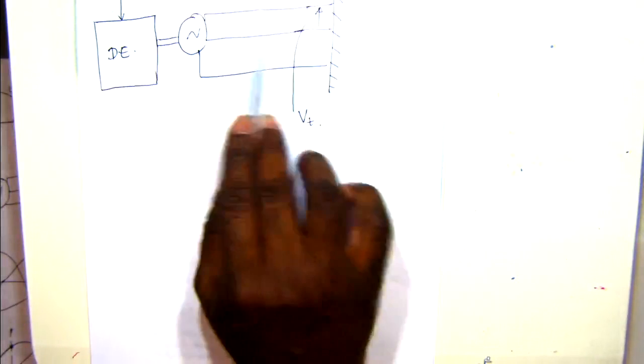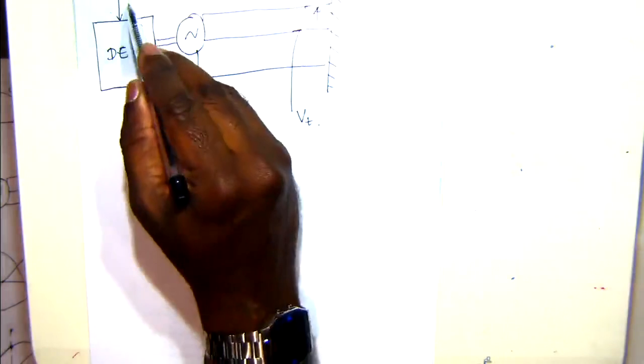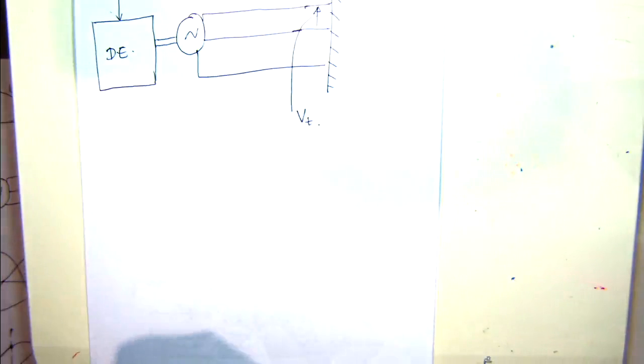Since this is connected to the grid, it's fixed at synchronous speed. So the synchronous generator speed can't change after you've synchronized it to the grid. It can only change in phase. Although you are inputting more fuel into the generator, the synchronous generator can't accelerate, so it transfers that power into the grid. That's one parameter, and the other parameter that you can control is the field excitation.